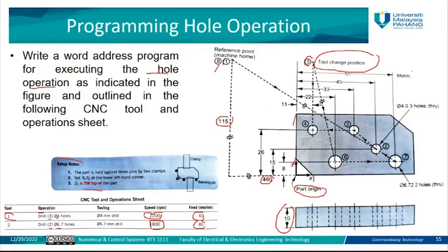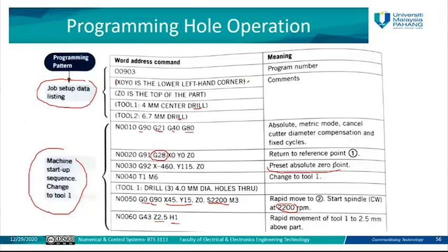If you do not make the correct coordinates for the spindle, it may not go up enough from the workpiece, so it will affect the shape and so on. So it's just to emulate the real operation, but to run such G code, you need to use either the simulator or the specific simulator that this G code was generated in, or to use the real CNC machines.